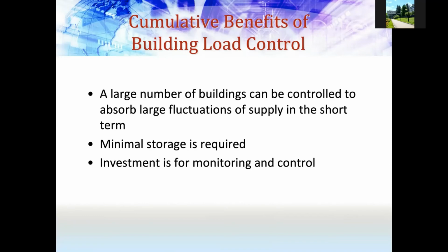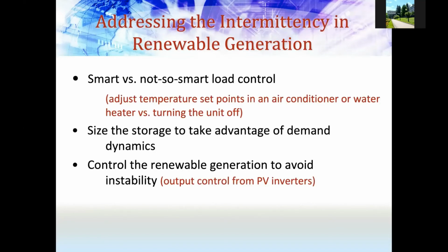The main investment you are making in this case is not the battery, but putting sensors in the building to monitor the temperature, humidity, noise, all of that, and control them. This is the difference. So some battery, yes, but not a lot of batteries, focusing on demand side control. So this is how I plan to address intermittency in renewable generation.